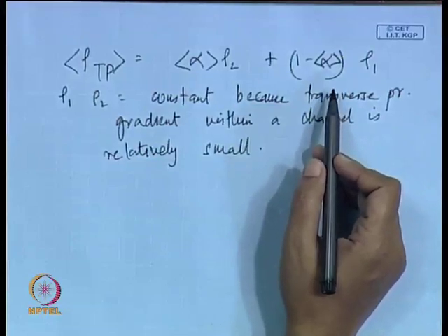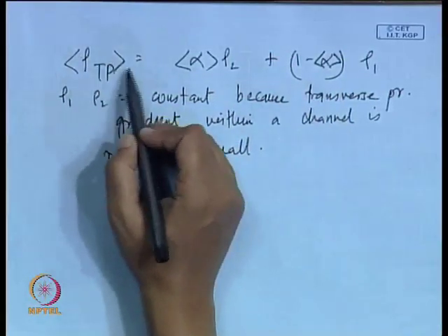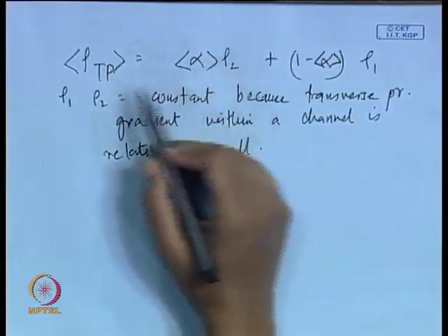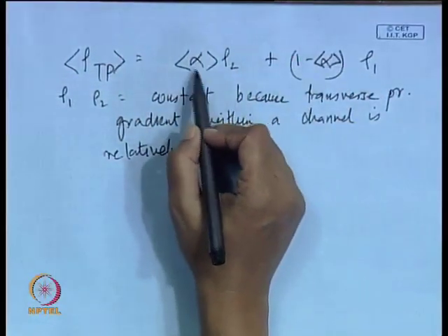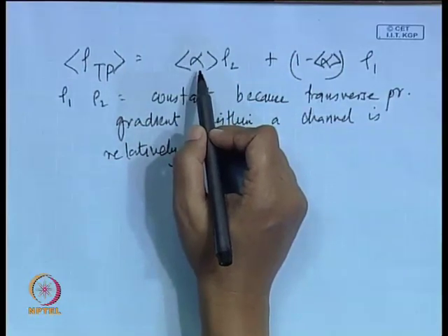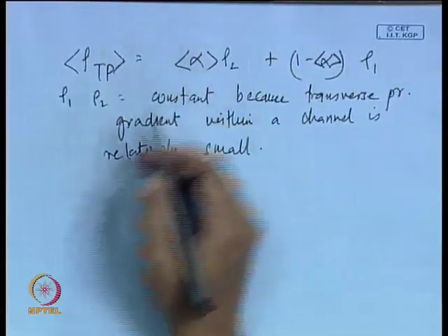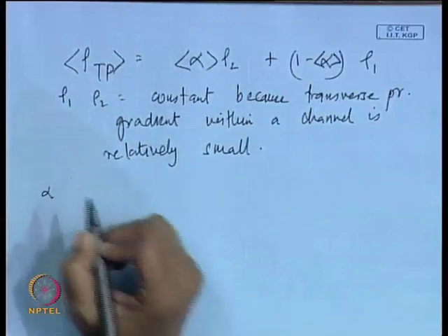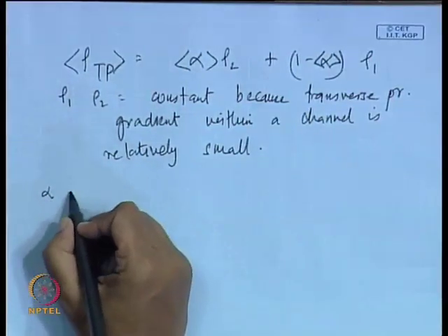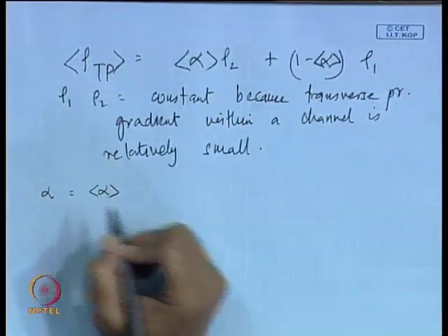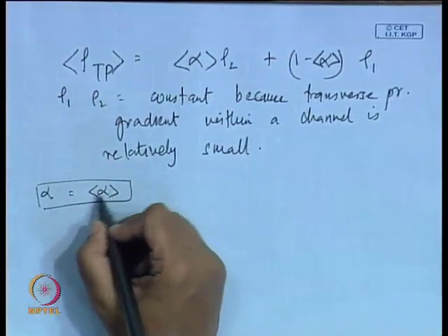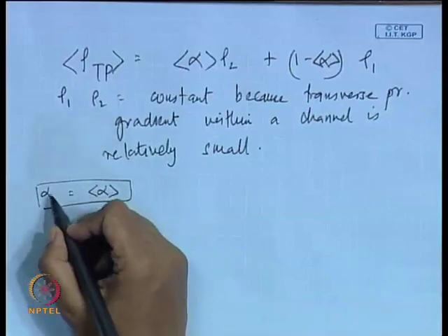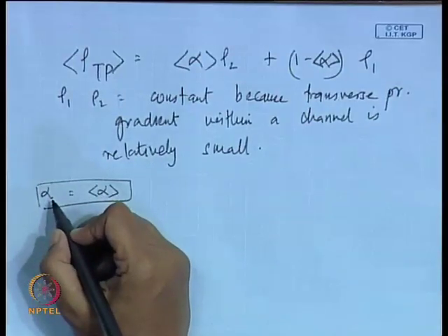Remember, after we finish the drift flux model, we will not be putting curly brackets everywhere because it is very cumbersome, but we will imply that when we just say alpha, it is the area averaged value. It is implied that after this particular topic is over, when we write alpha, we mean this, unless otherwise stated, because every time writing this down is difficult. So, when you express it as alpha in this way, it is the mean averaged value.